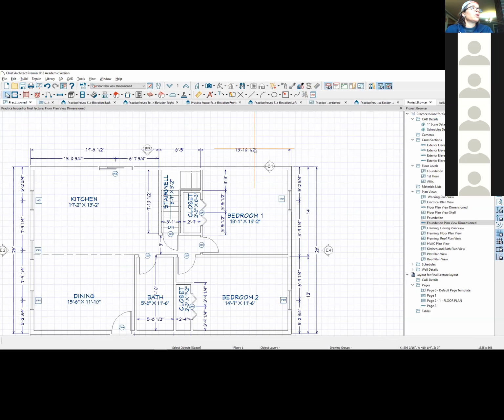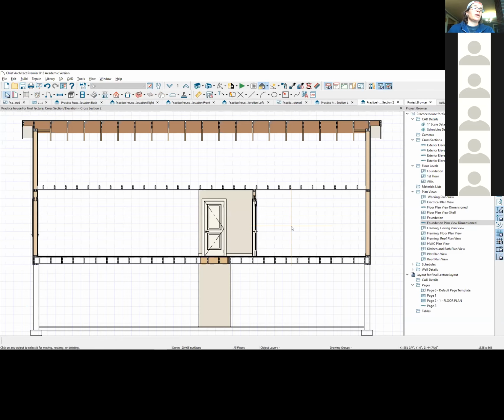If I do a back clip cross section here, I'm going to see something entirely different. I'm going to be looking at the edge of my rafters. So let's see what this back clip cross section looks like. It looks totally different. I'm slicing through all my joists and I see all their ends, and here's my ceiling joist and here's my rafters where they got cut, and then just the amount visible of their undersides for that distance that I've back clipped.